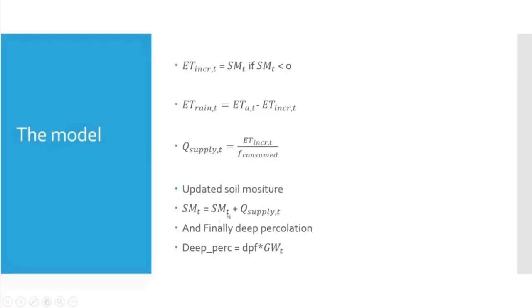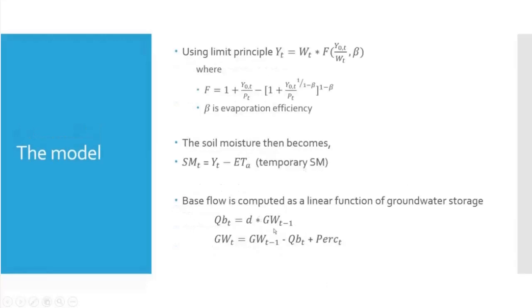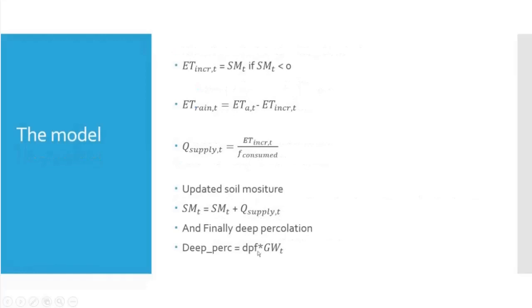And the alpha, which is the catchment retention efficiency, which we can relate with land cover, but this retention parameter also depends on some other factors, like the weather condition, the antecedent moisture, soil moisture condition, the slope, the soil type. So we included a parameter also to adjust this catchment retention parameter. So we have 3 parameters for this model.